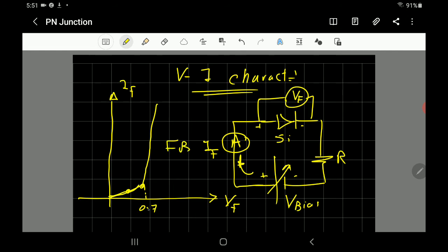So it means before 0.7 volt, which is the barrier potential, the current is very small and the diode is not conducting. But once it hits 0.7, the current increases rapidly because the material, like a short circuit, becomes conductive. The voltage across the diode stays very small, from 0.7 V to 1 volt. It doesn't matter how much you increase the voltage, it doesn't exceed a small amount, but the current increases rapidly. In a real diode, this axis is milliampere, and this is voltage. So that is the forward bias region, the VI characteristic.